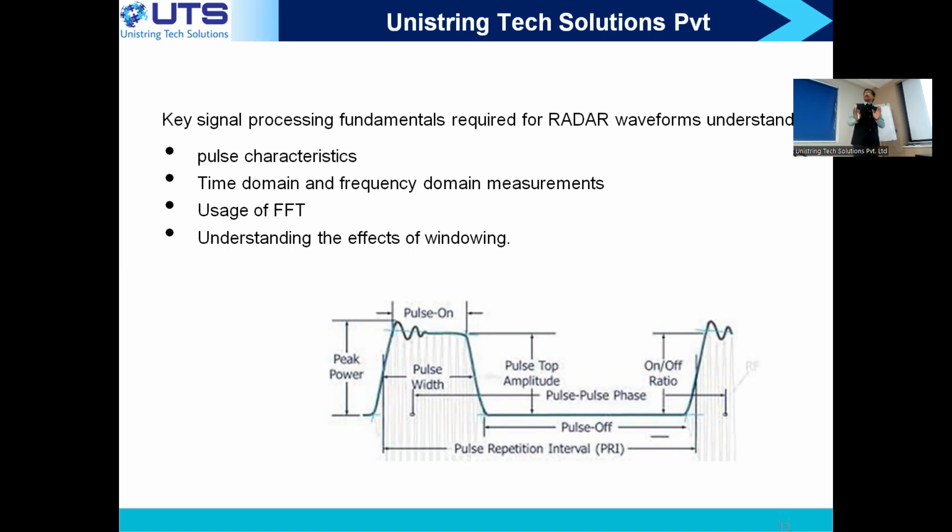Radar can be built basically by, see, I send a pulse and I keep waiting for the receiving signal. When I receive a pulse, I measure the time difference, isn't it? And based on that, declare the distance. Okay, and I know what frequency I'm sending. I will measure what frequency I'm receiving. Rather, I will measure the difference of frequency. Then it will tell me the velocity of the target also.